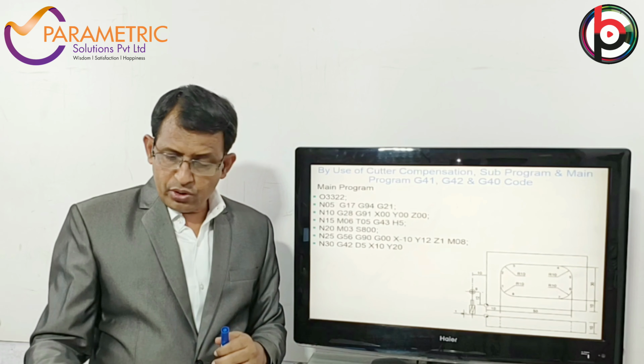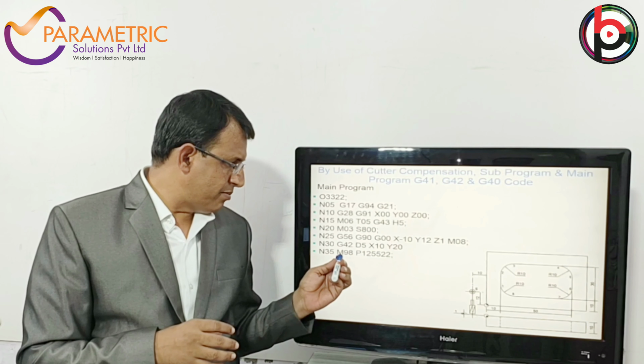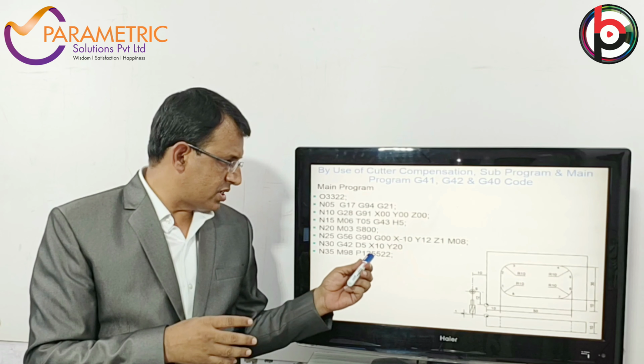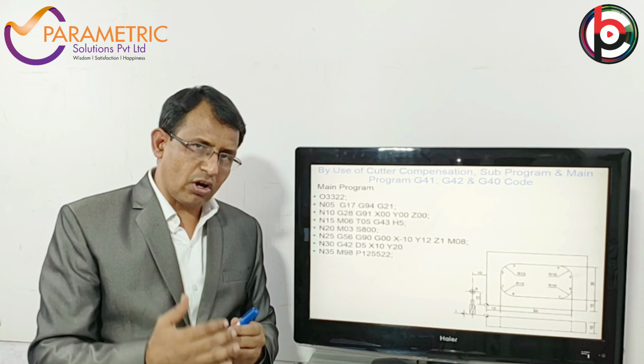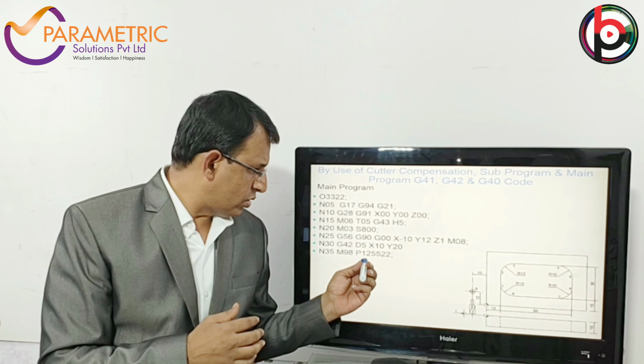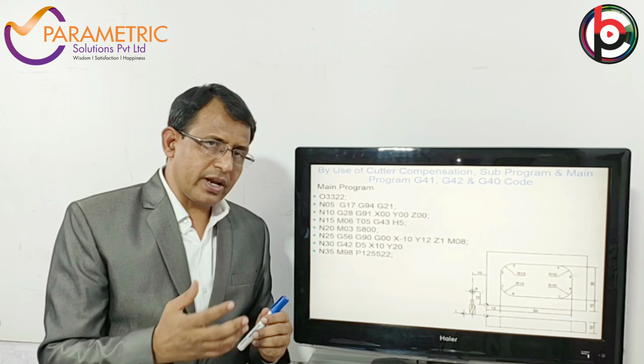From here, we are going to call a subprogram. The subprogram is always called with M98. The program mentioned in the earlier slide, 5522, we are calling, and that program is repeated 12 times. What do I mean by 12? That is P12, and 5522 is the program number.